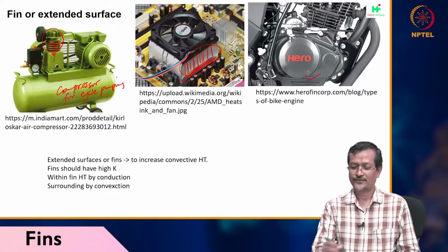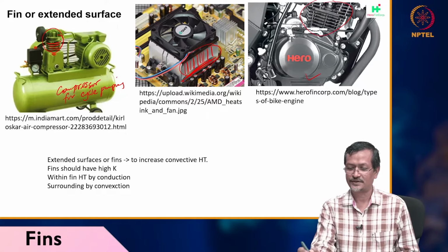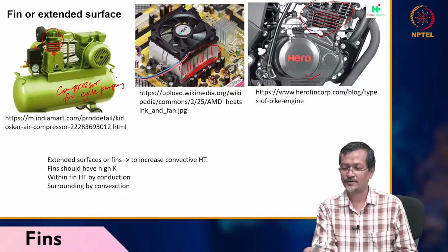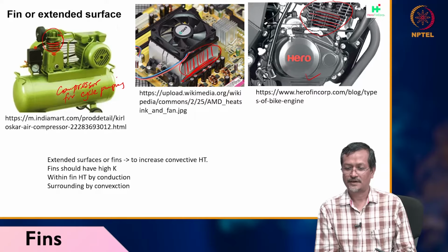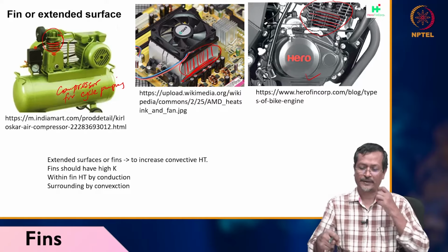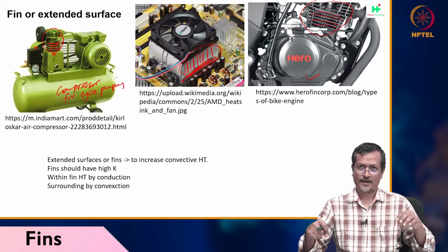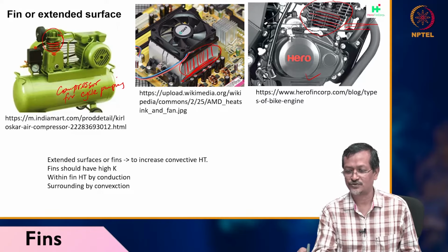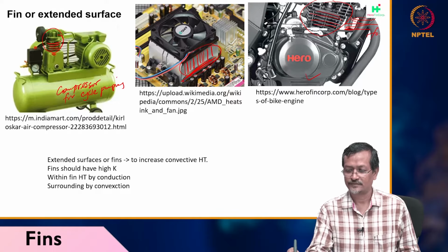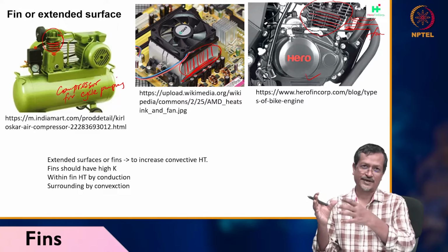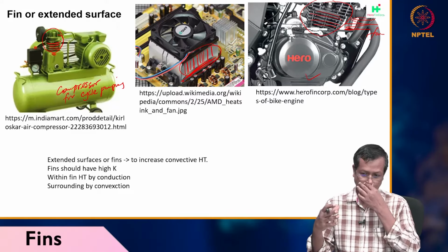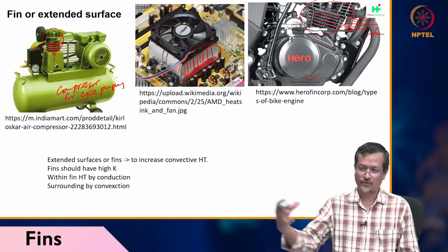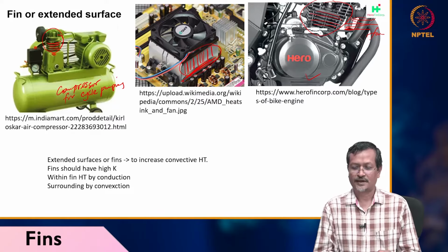And in a motorcycle, if you see, there is an engine with a piston cylinder arrangement and these are the fins. Those fins reduce temperature. Normally when you are not driving, there will be natural convection because there is no air blow, and your engine also takes less power. But when you are driving, the engine takes more power and generates more heat. At that time air also blows over it, creating forced convection. So they have created the engine outside so that whenever you are driving, air passes over the fins, creating forced convection, the heat transfer rate is higher, and the engine will be safe.